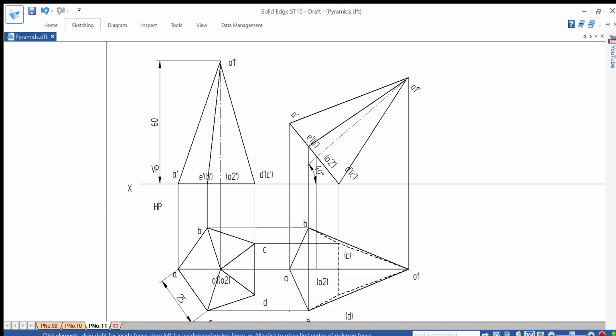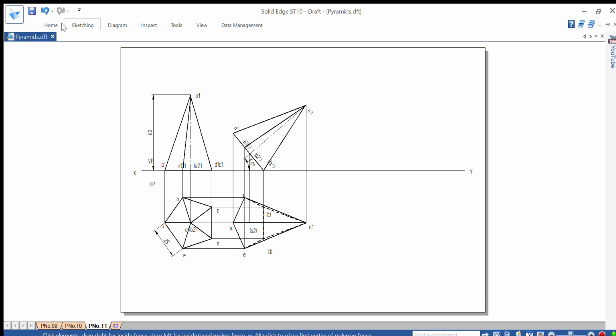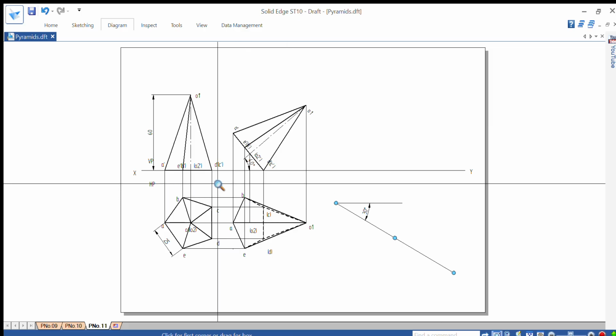And next, draw a 30-degree line in the third position. Go to the line command, take those thin lines, take 30-degree, taking it a little bit down, draw the line, go to angle, from this line to here 30. You type 30, it will change to 30-degree. On this line, this B and C have to be placed.